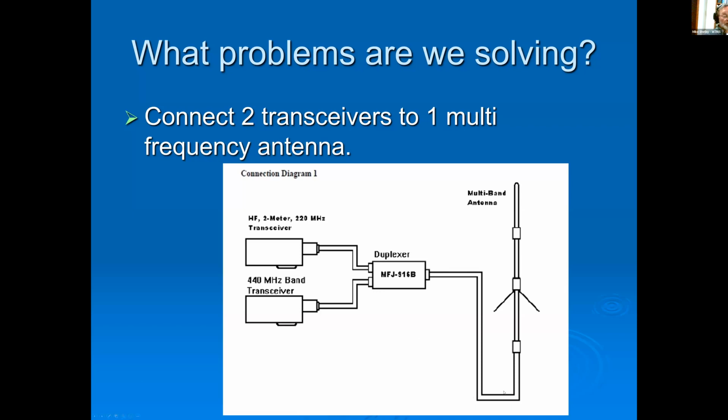And then I can talk to that antenna. That duplexer will direct the receive and transmit for whatever receiver onto that coax. So the neat thing is that we know if we take 2 transmitters and tie them together and put an antenna out there, we transmit on one, the chances are we're going to blow the snot out of the receiver on the other transceiver. So the important thing that this guy does for us, it provides isolation.